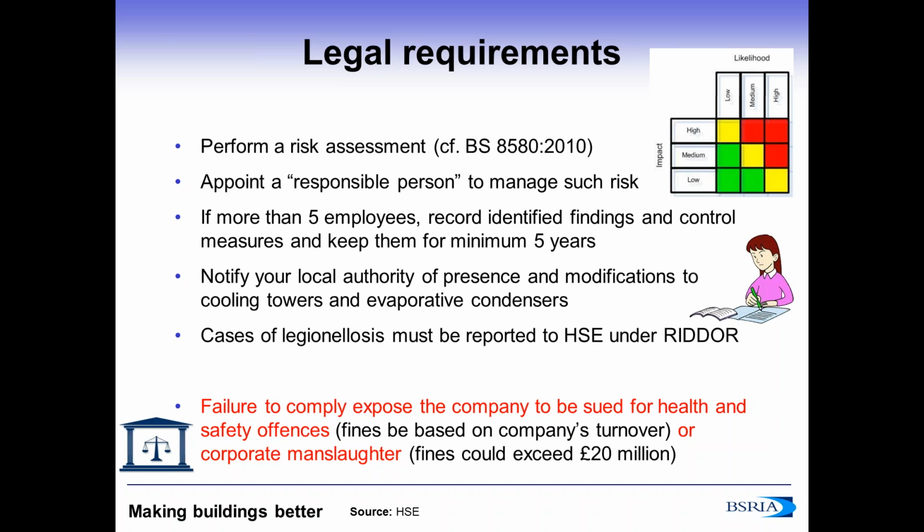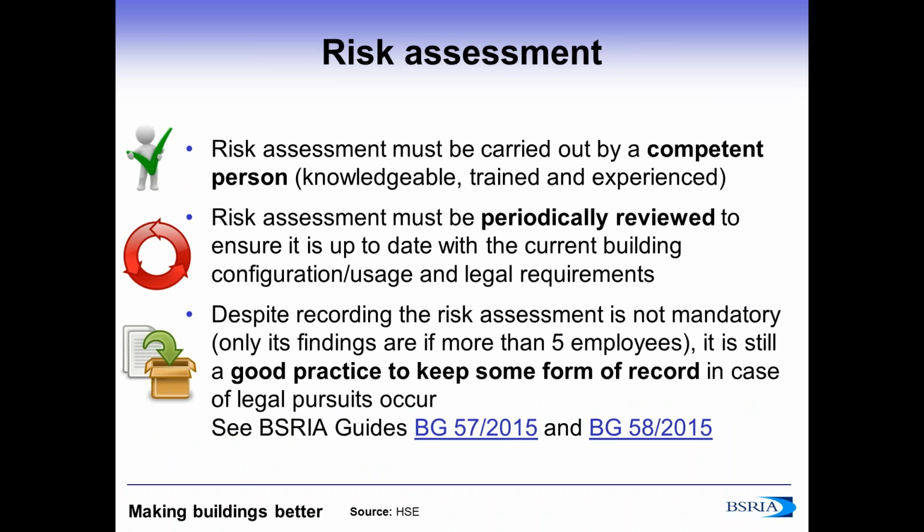Failure to perform or enforce them could result in breaking HSE regulation or being sued for manslaughter in case someone dies from Legionella disease. So it's crucial that a risk assessment is performed for all the water systems in the building and how they are likely to expose occupants, permanent or not, to Legionella.